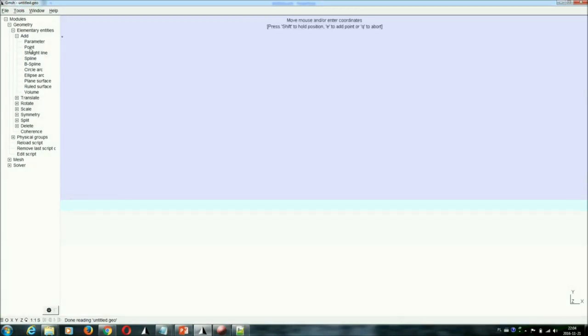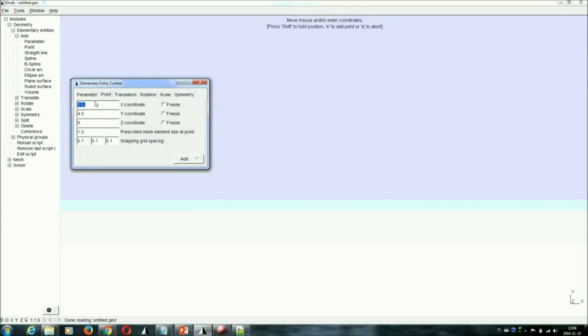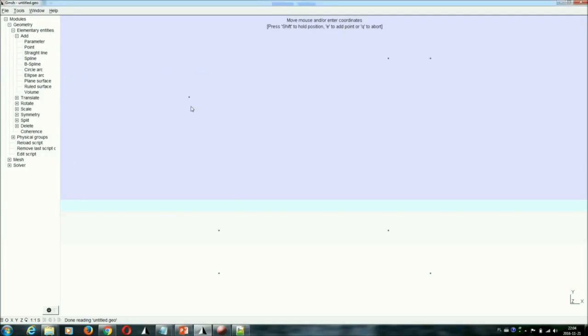Alright, so let's start creating points. Let's start with 0, 0, 0, add point, then let's change x to 5, y to 5, then x to 4, y to 1, and finally x to 0. So we've got points distributed here, here, here, here, here, and here. And what we are going to do is we are going to create an L-shaped geometry.